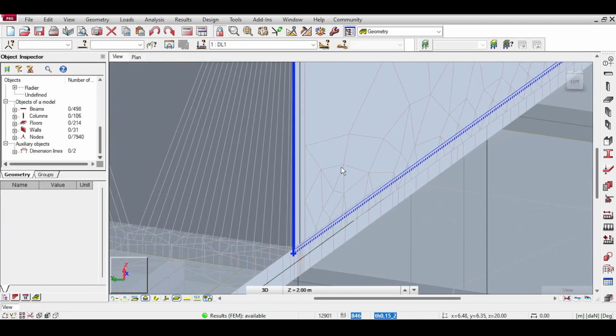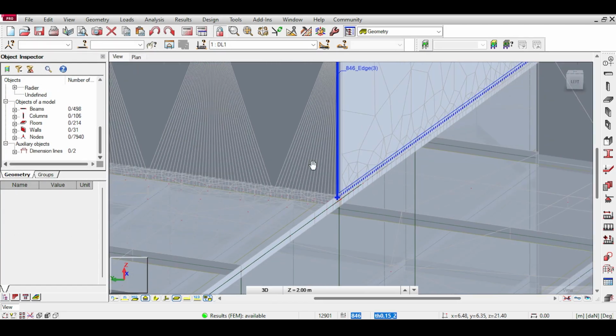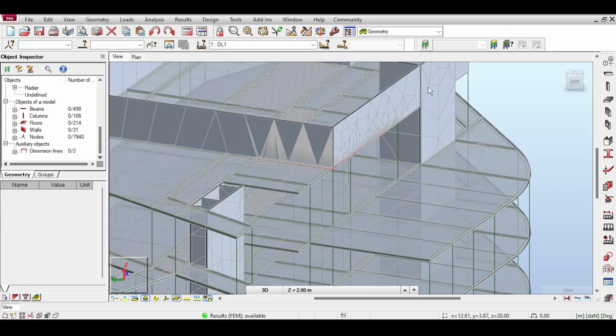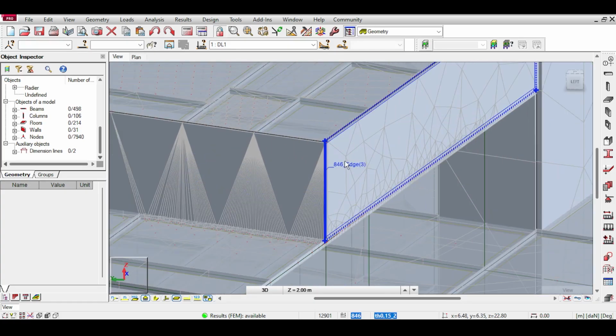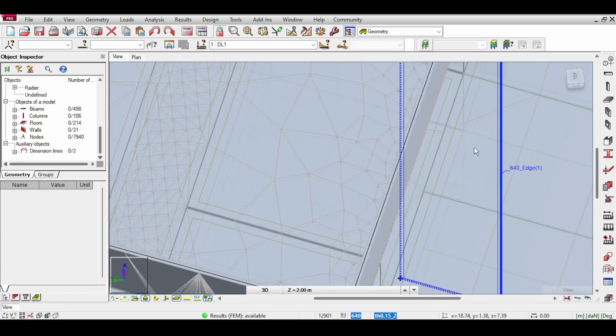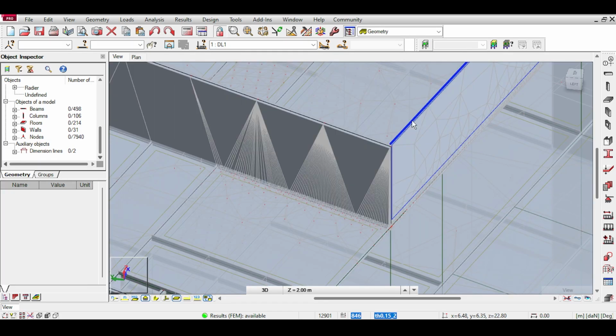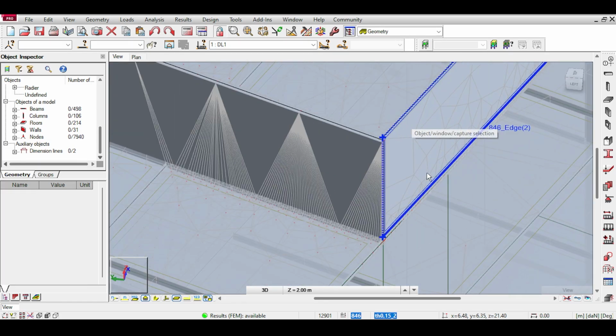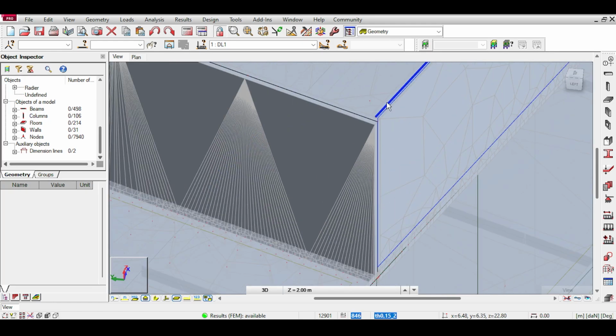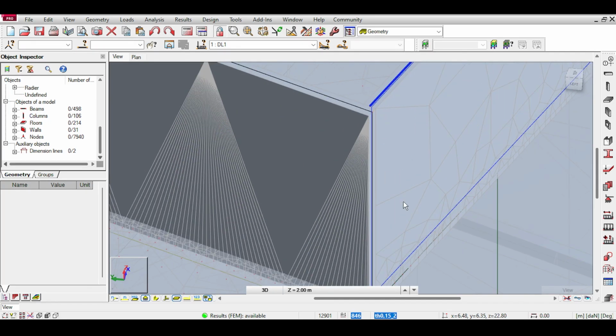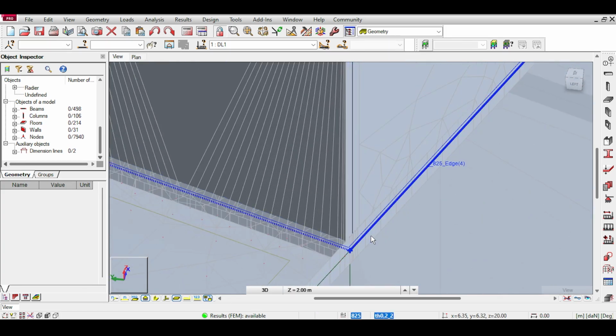Yeah, there we go. This is exactly what he sees in Revit. I think I know exactly what happened. You model your structure in Revit, I think, and it looks perfectly fine. It looks very nice, and you can see all the edges seamlessly click in place. When you export this to Robot, problems break loose because in Robot, it doesn't consider the thickness of the wall. It actually only considers the center of the wall, and that's why I have the misalignments here.